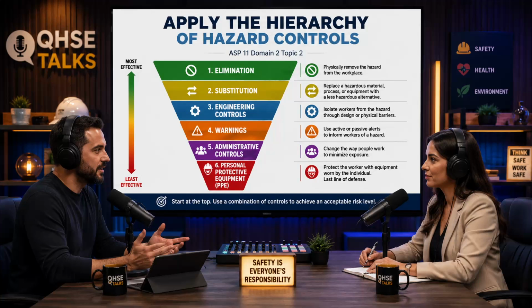Exactly. Let's analyze the mechanics of that trade. Ethanol is still a hazardous chemical. Right. It is highly flammable. Yes, but compared to the severe toxicity of methylene chloride, it is a significantly lower risk substance to handle. So you haven't achieved zero risk because you still have to manage the flammability of the ethanol, but you have fundamentally downgraded the severity of the potential harm. Exactly. Another classic example you'll see is substituting toxic solvent-based industrial paints with water-based alternatives.